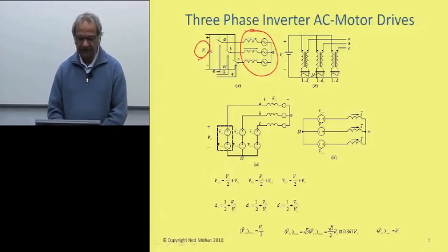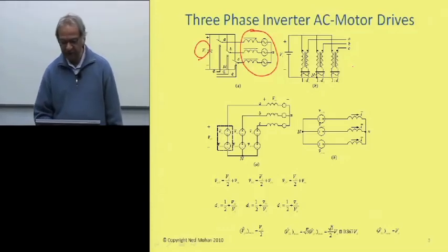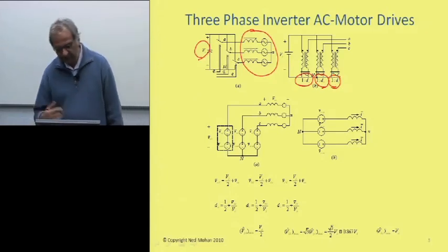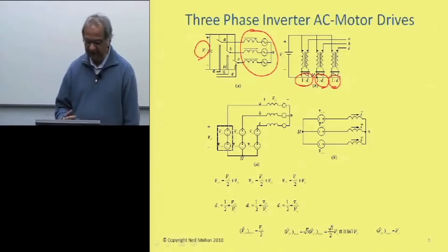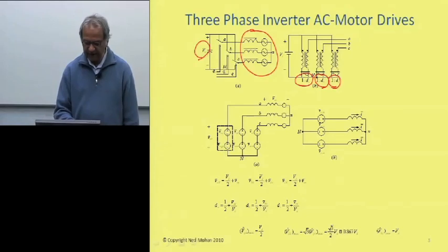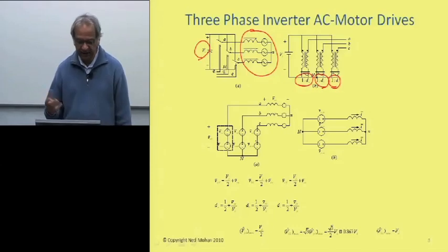So you'll see that if we can replace these switching power poles on an average by these three ideal transformers with controllable duty ratios, where the duty ratios are the turns ratios, given by 1 to dA, 1 to dB, and 1 to dC over here, right? So following what we have seen in the case of the converter for DC motor drives, what is going on is that we once again introduce a common mode voltage in all these three poles.